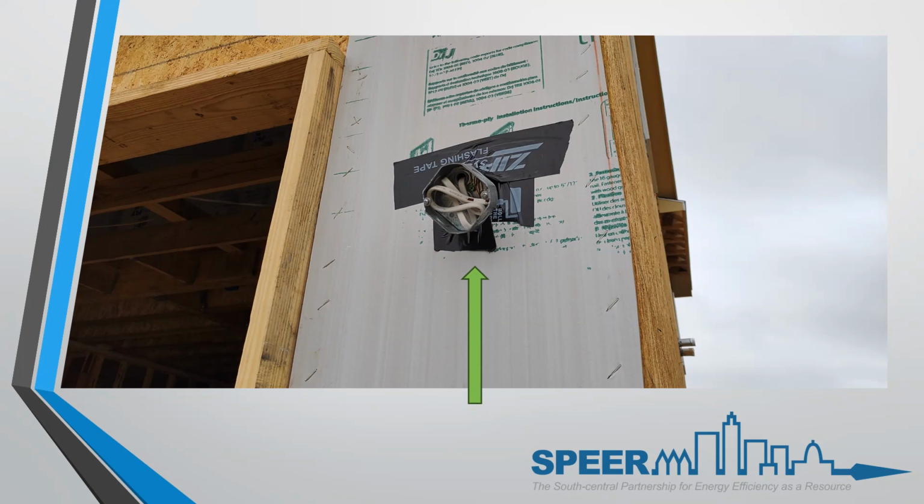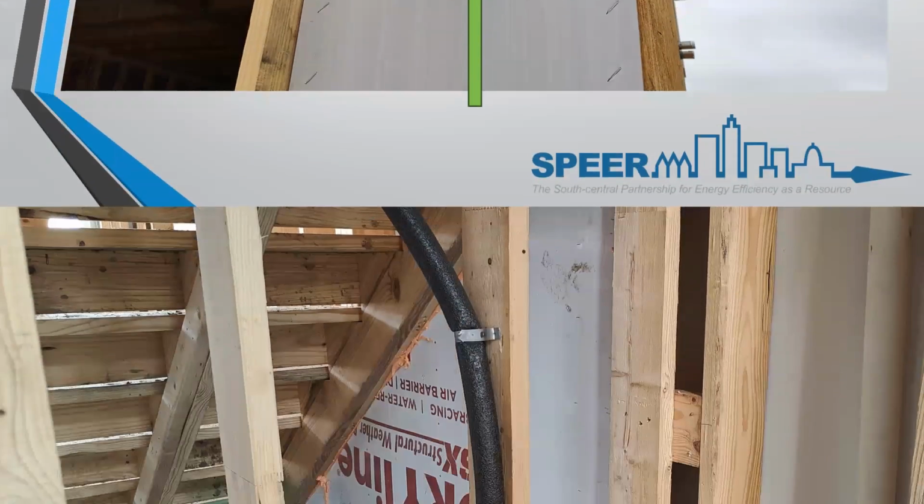It's only saying the type of material that should be used, like foam or caulking or other approved means for air sealing. And that approved means is usually up to the CBO, the chief building officials or building officials in that area. They're the ones that can decide whether or not the material being used or product being used meets the criteria of an air sealer. So that's kind of up to them to do. It's just left to general terms of material type.